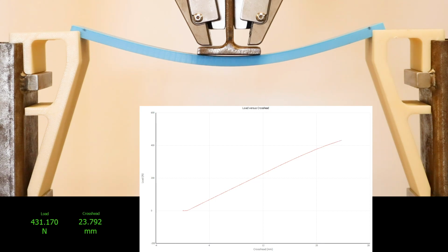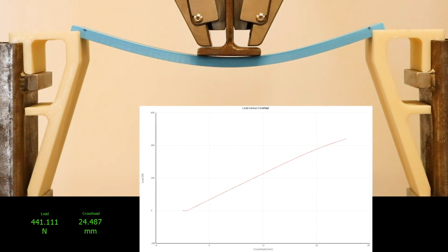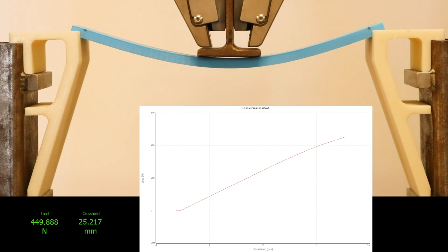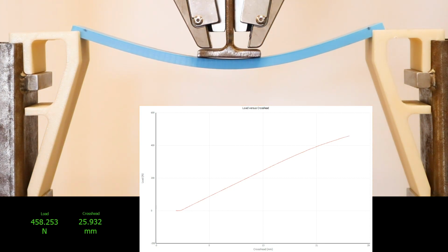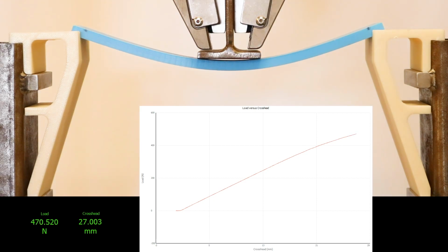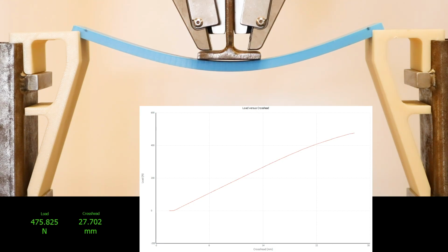You can also see that our markers that we added, those black markers, have started to move away from the supports a little bit there. So we've got some horizontal translation going on between the beam and the supports. So that tells you something about what sort of supports you would model this beam as having.